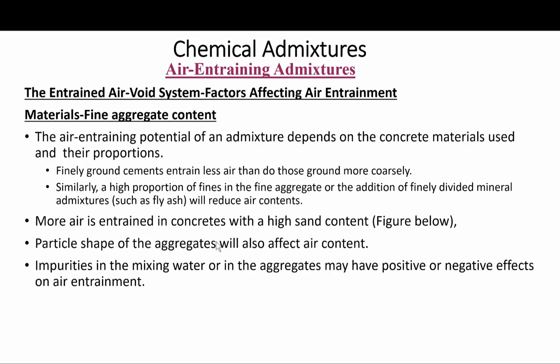Also, some common chemical admixtures, for example superplasticizers, may interact when mixed with air-entraining admixtures and inhibit entrainment. In such cases, the second admixture used in addition to the air-entraining admixture should be added to the concrete after the air has been entrained. That's one way to deal with it.